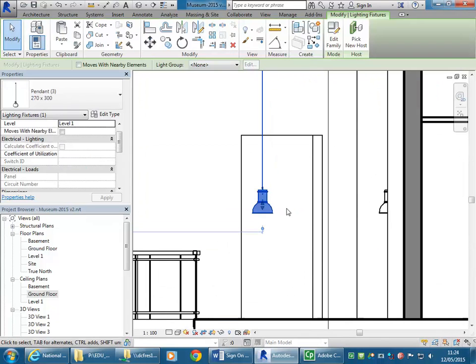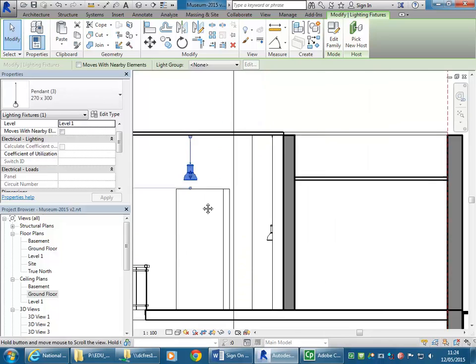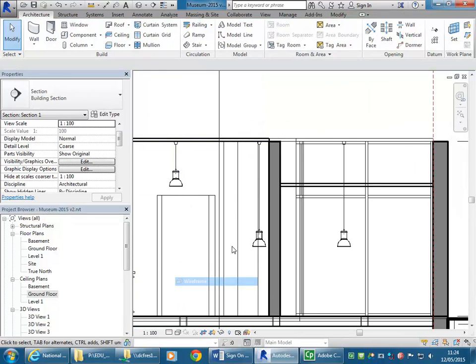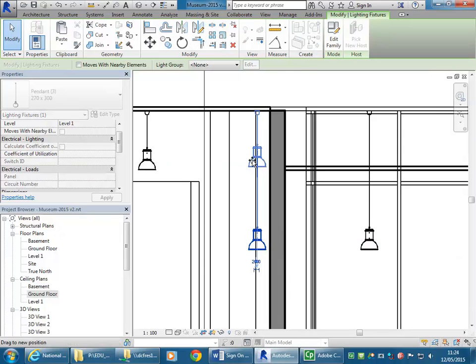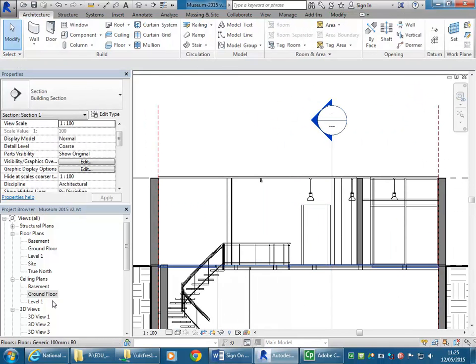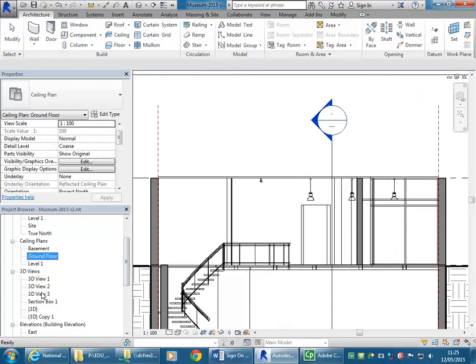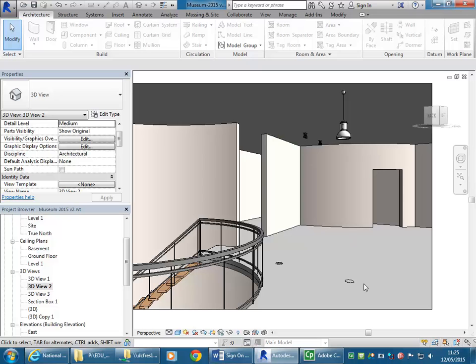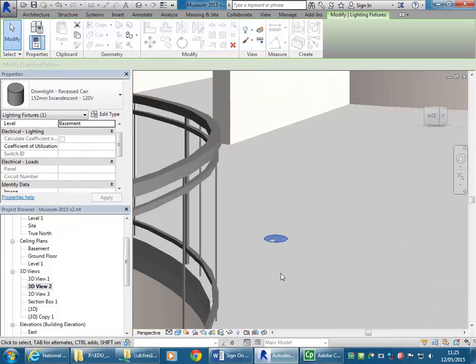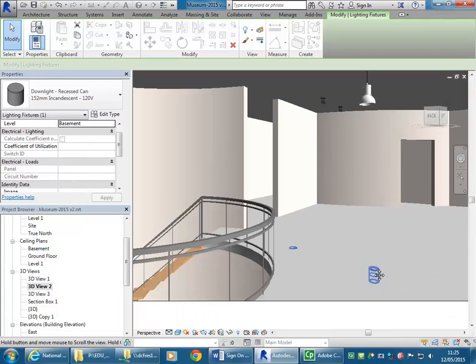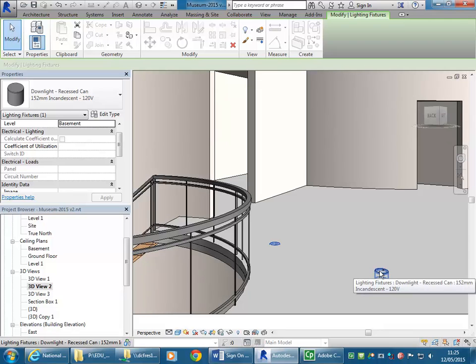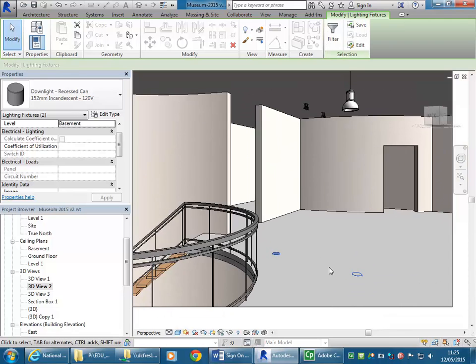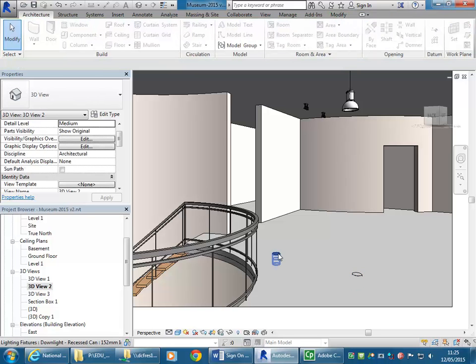And then also we can look at things like the height of these pendant lights. Maybe just in wireframe for the others. So it's a really helpful thing to have a few perspectives set up that you can do test renders with. Oh, now there, if you had that issue, because we really did push the floor thickness to be fairly small, you could hide those or have a look at editing the family.